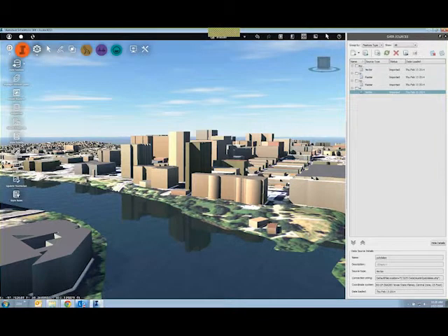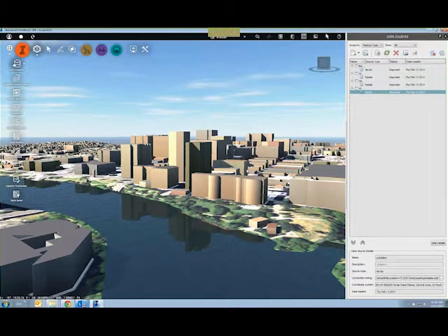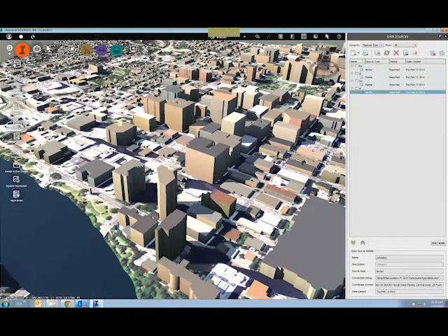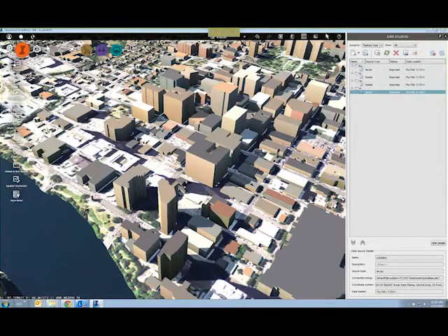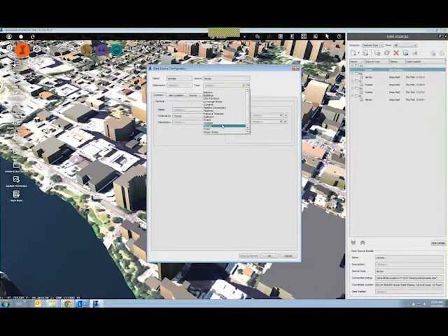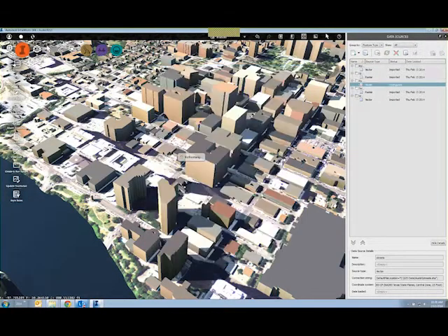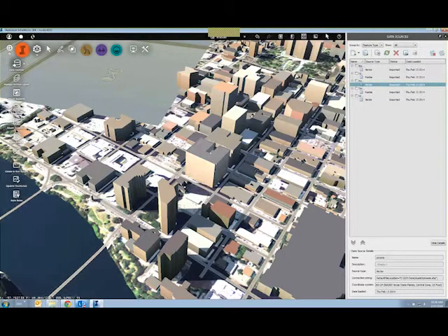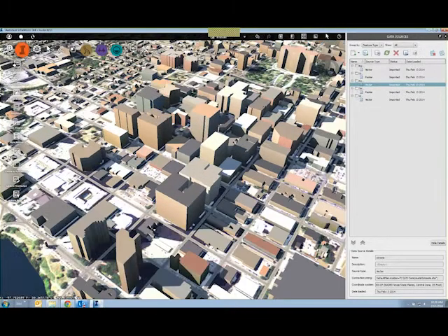And we'll go ahead and add in some street information. Now, again, GIS information, simply telling it that this is a road. Close and refresh, and this will process for me all of the streets in Austin. And you can see now I've got some roads across town. I have all of the information on these streets in this area. And you can actually use some of the metadata, the data about the data, that's in these shape files to control things like street width, the number of lanes, the style of road that's displayed. And we'll look at that in a second in a little more refined Austin model.